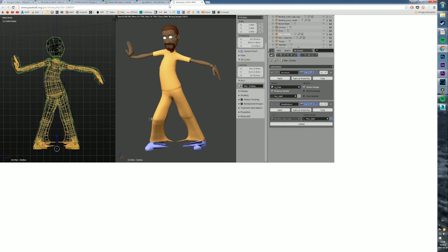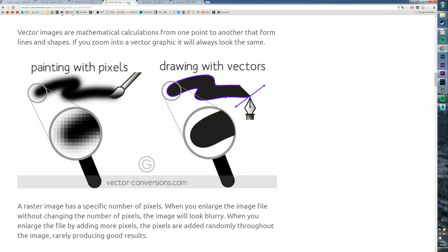So mesh models are more for game visualization and so on, but they're also a product of a solid model. So you can take a solid, you can convert it more or less into an STL file, OBJ, and so on, and use it for polygon applications. So I hope that clears up a little bit where to use it and how to use it. So for my viewers, you're mostly 3D print oriented, so you want to use something like solids or surface models and then export into a mesh format for the printer. I will probably see printers taking the solid formats in the future as well, but that's the whole goal.